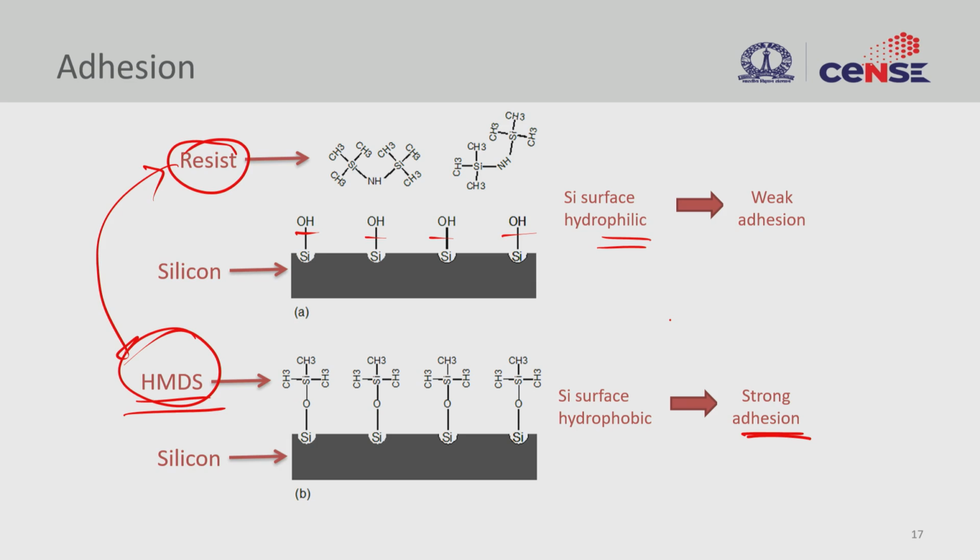It creates a polymer chain that promotes adhesion between the substrate and the polymer that you use as photoresist. Once you have the adhesion promoter in, you can be assured that the resist will stick onto the wafer nicely, and also that your patterns are nicely aligned.